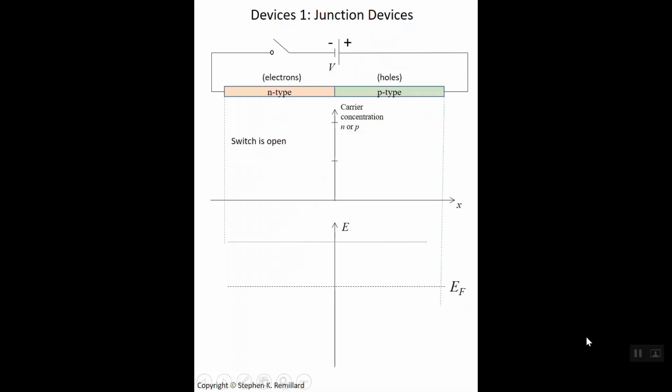A p-n junction is made from 2 types of semiconductor materials, a p-type hole-doped material and an n-type or electron-doped material. The prototype we'll illustrate with here is a single ribbon of semiconductor, all one material, perhaps silicon, formed by diffusing donor dopants and acceptor dopants into it one at a time. First, the right side was masked off and donor dopants were diffused in, and then the left side was masked off and hole dopants were diffused into it. The result is this ribbon that's half n-type and half p-type.